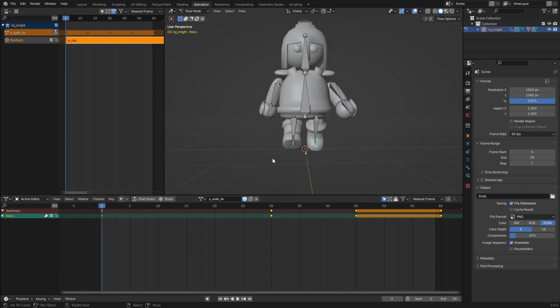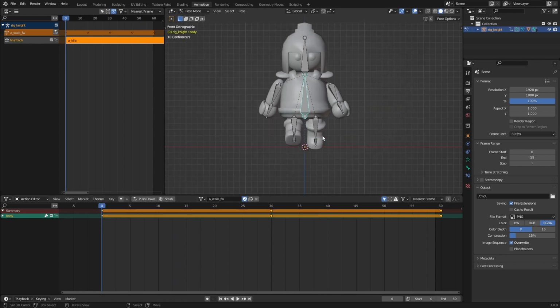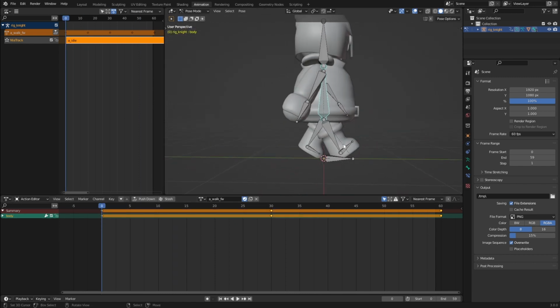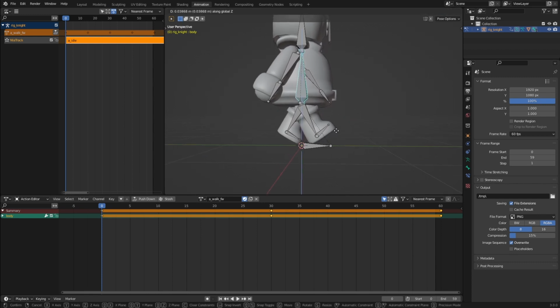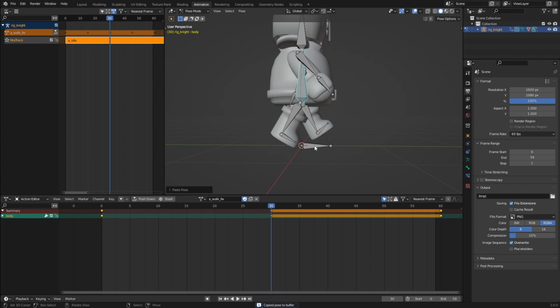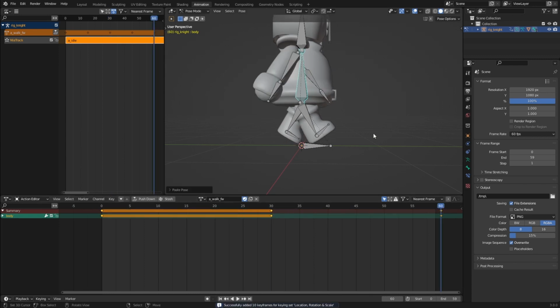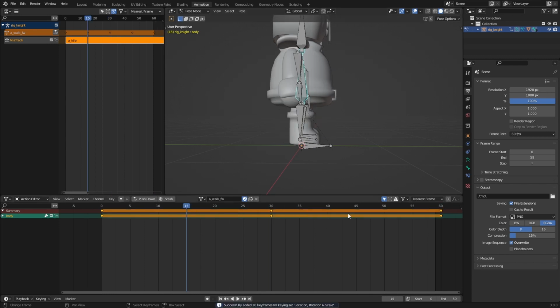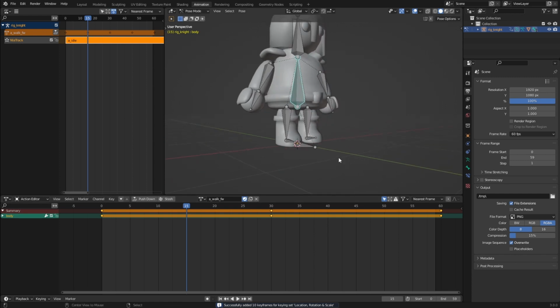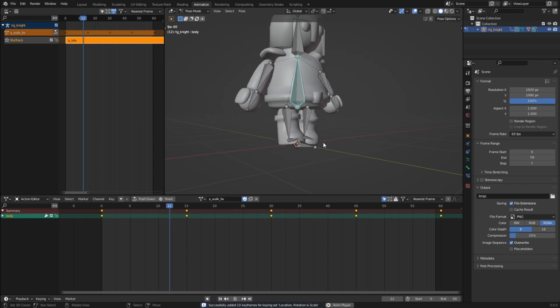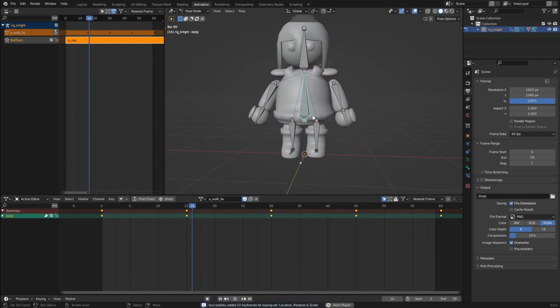And also what we can do is select the body bone, and whenever we're transitioning between steps, you can just move the body a bit up, copy, paste, I, and paste I. And then on frame 15 and 45, I'm just going to press Alt-G on the body bone and press I. So now we also have this little up and down motion.